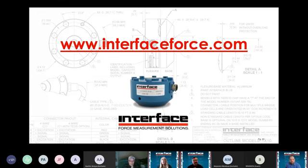Thanks, Keith. We did get a question from Dave. He's asking, is temperature compensation achieved using dummy gauges? And the answer is no. We do temperature compensation of output by matching the strain gauge to the material. Temperature compensation of zero is done by adding, say, wire into the circuit that has equal resistance change, or I should say opposite resistance change to the circuit.